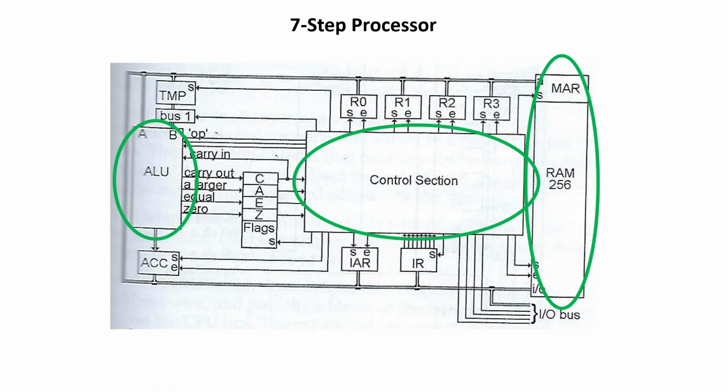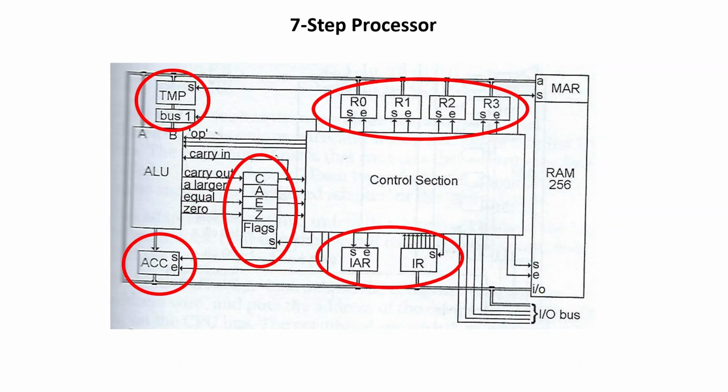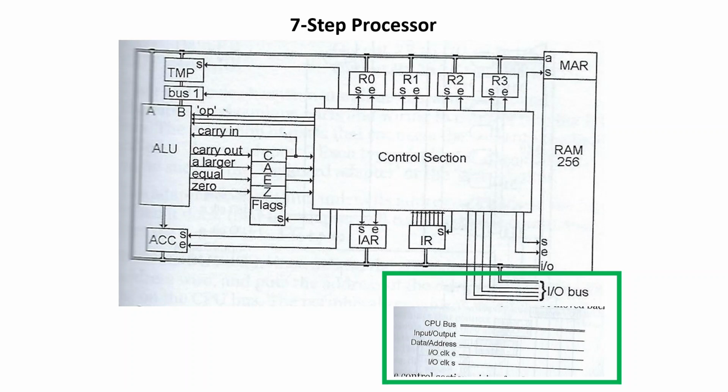By the end of part 4, 3 main components of the processor had been described and verified using Verilog: the main memory, the ALU, and the control unit. So the next thing that needed to be done was to write descriptions for the remaining smaller components of the processor, and then put all those modules together into one processor description. For the processor description, I/O ports needed also to be taken into consideration, and so that's what I did. I wrote those remaining modules, put them together into one processor module. Then I developed test circuitry for verifying the processor.